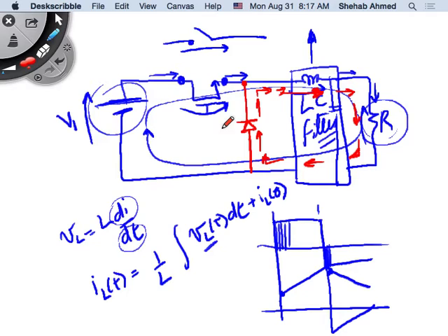If you go back to your 322 material, you will know that you can calculate the inductance of this circuit. There's a magnetic field set up around the wire, so the circuit has some inductance. So when you turn on and turn off the switches in your room, you will see arcing, and that is because of the inductive effect that we just talked about.